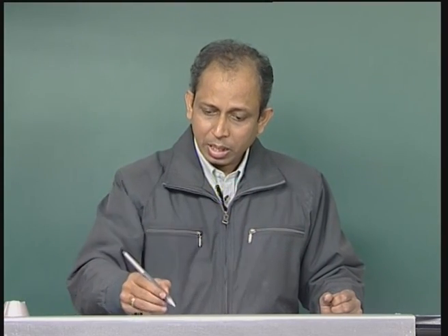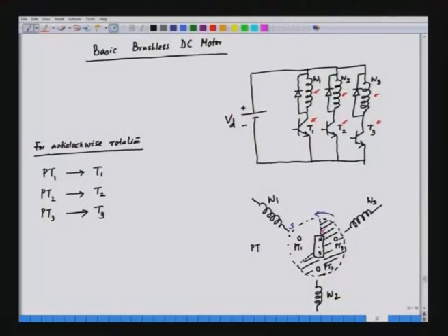So, there has to be a position encoder like the present case. We have 3 phototransistors and we have a disc, partly opaque and partly transparent, and in this case we make this 120 degree. This is 120 plus 120, so that makes 240, and this is 120. So, when we make this disc, 240 will be opaque and 120 will be transparent.